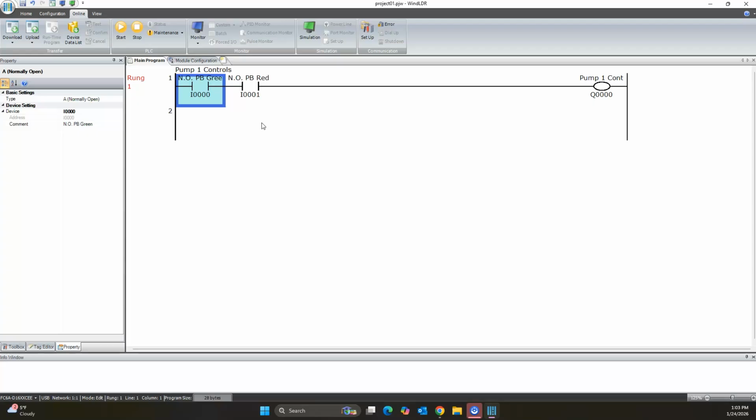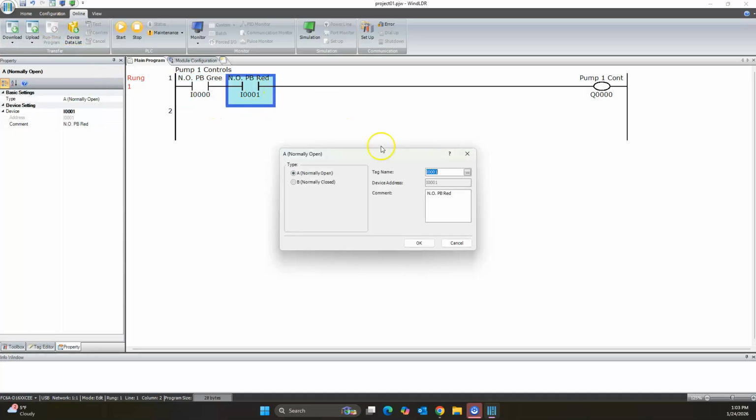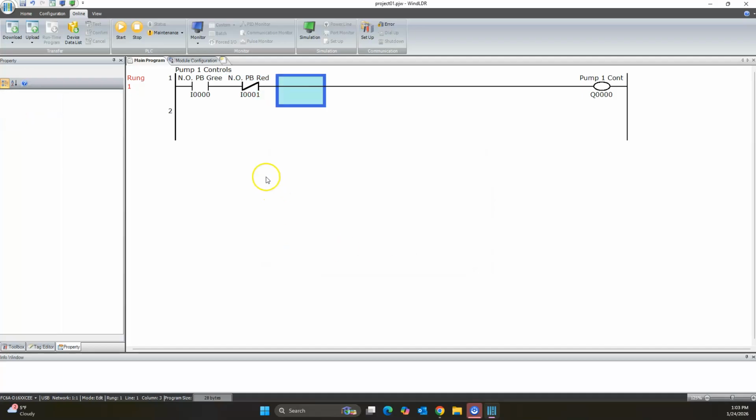So if the input is true, it's high, there's voltage, right? It's a 1. This normally open or make instruction will make logical continuity. That is the key distinction between a break instruction. Let's put in this normally closed, or what I will call a break instruction.